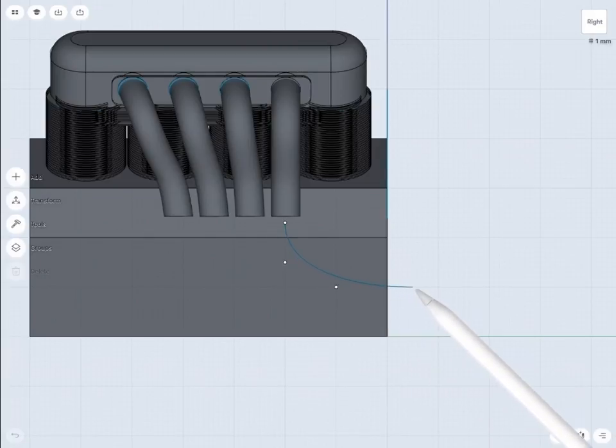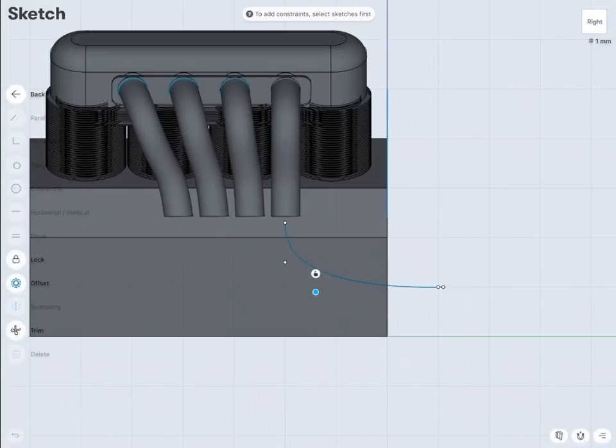Yet again, I'm going to use the sweep command to sweep along that spline. Make sure the spline is not very curvy, otherwise the shape might fail when being created. Just some more teeny adjustments. Make sure to align all of the bottom spline points at the same level. It will make your pipe look smooth and more continuous.